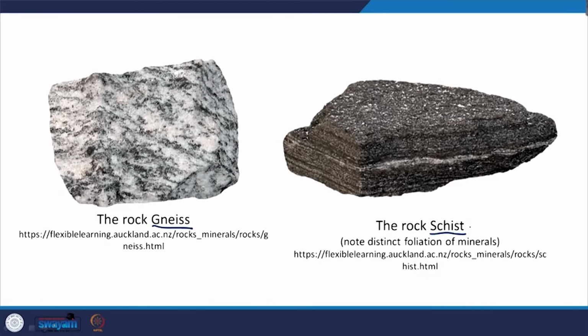This gneiss rock is formed by the metamorphosis of granites or the sedimentary rocks, and as the picture shows, it displays distinct foliation representing alternating layers composed of different minerals. So, unlike slate and schist, gneiss does not preferentially break along planes of foliation because less than 50% of the minerals which are formed during the metamorphism are aligned in thin layers.